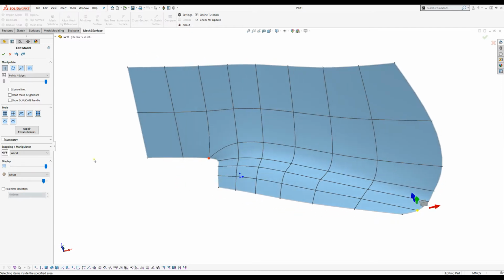The other option is called split edge. The split edge is useful in some cases, for example, when we want to create another split but only in one direction. For this reason, what we need to do is just select an edge. This will mean that it will follow all the quads that are connected in this direction and just split these edges in half. Let's try this command. I will just select my edge and press split.